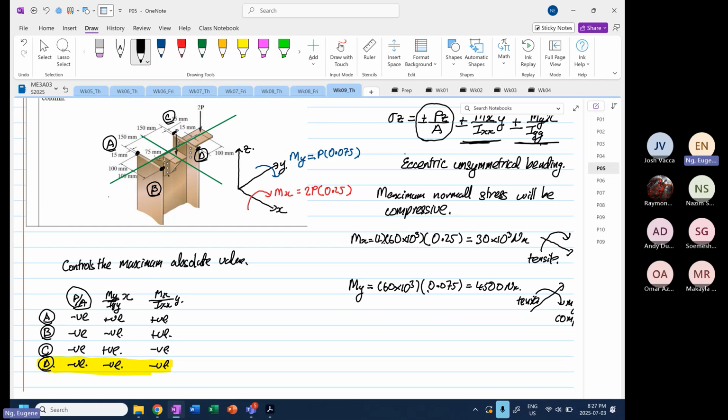Okay, so we look at our Ixx. We just need to be careful over here. So XX, the width is equal to 0.2. The depth is 0.3 cubed divided by 12. So this is a solid rectangle I'm taking. Then I'm going to minus the two sides, the two smaller sides. And then we also have the I, right?